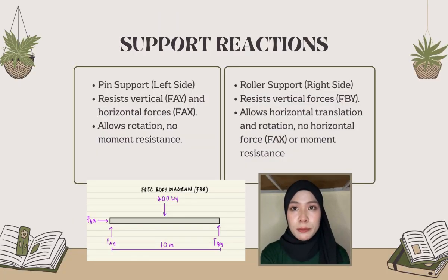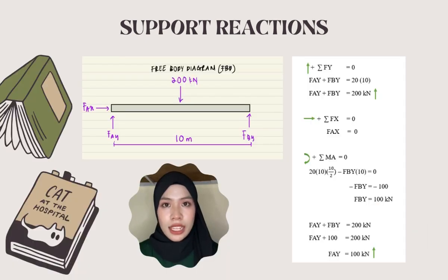This slide shows the bridge support reactions. The left pin support resists vertical FAY and horizontal FAX forces, allowing rotation. The right roller support resists vertical force FBY, allowing horizontal movement and rotation. This support ensures the bridge stability and load distribution.